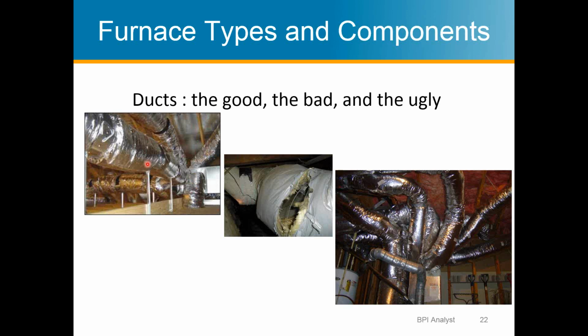HVAC guys love to hang them from the ceiling. There's some weird thing written in the California code about how they should be attached, which can be interpreted a few different ways. Some building inspectors will not pass you if they're not hanging in the middle of the air in the attic. Talk to your building inspector. Hopefully he'll let you just lay them on the floor of the attic, and then you can put insulation over and around them. It just makes them even more efficient. It keeps more heat in. So ideally you wouldn't have them like this. They would be buried in insulation.